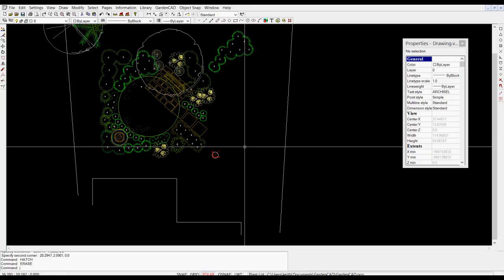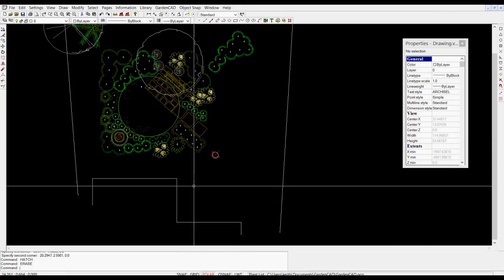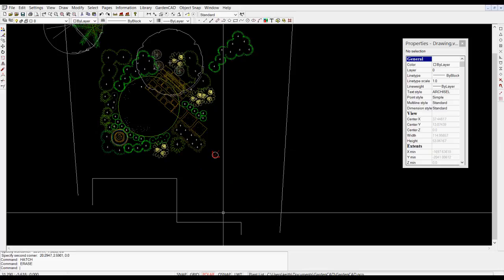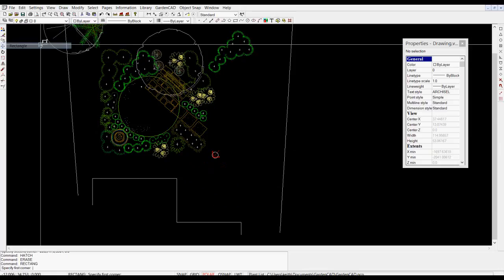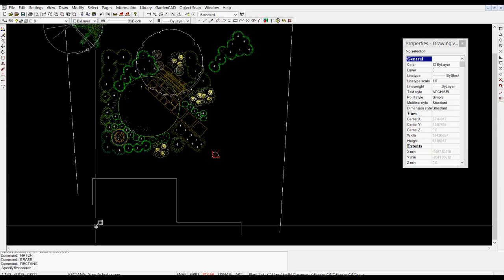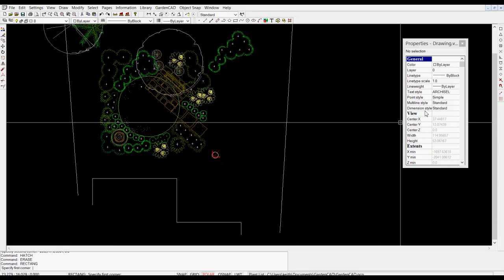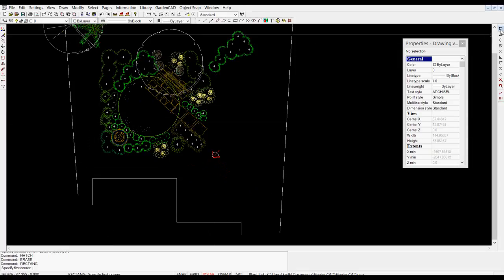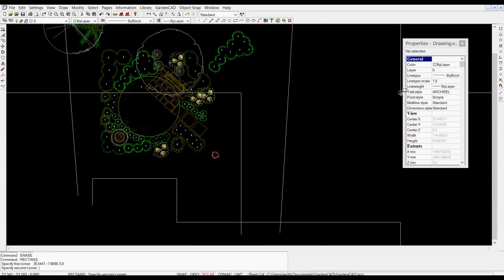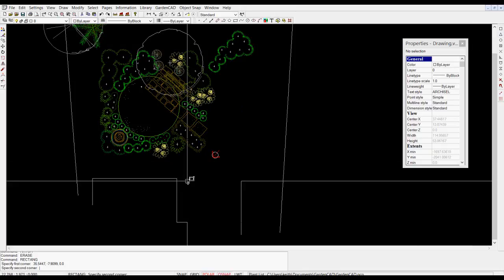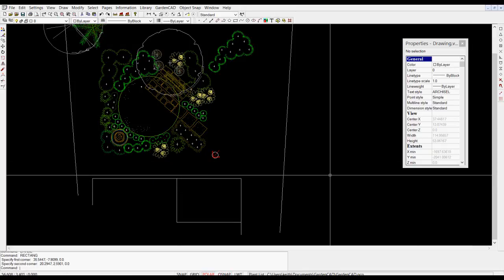The next step in developing this design might be to put a rectangle down in this area and we'd hard pave it. So it's draw, rectangle, and the prompt down in the command area says specify the first corner. Again, I'll use entity snaps, let the software do the hard work, it latches onto the appropriate point, and then for the second point of the rectangle we do that.